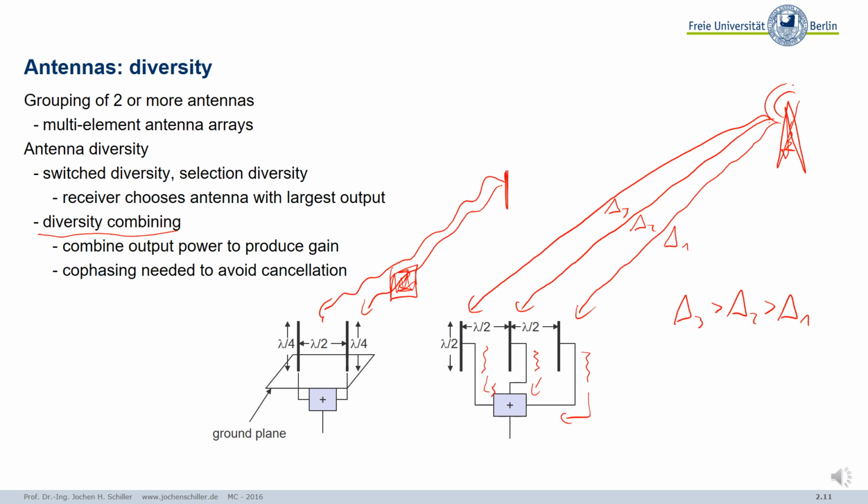If we now have the antennas spaced apart by some centimeters, this means a time difference of some dozen to 100 picoseconds. You might think, okay, come on, picoseconds, who cares? Think what happens. I mean, we are operating at whatever, 2.45 gigahertz, 5 gigahertz. 1 gigahertz already means one transition in your sine wave in 1 nanosecond.